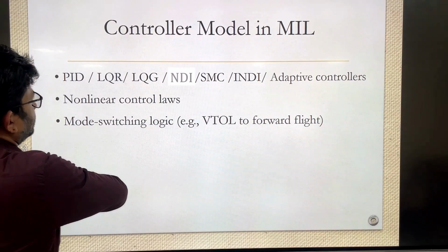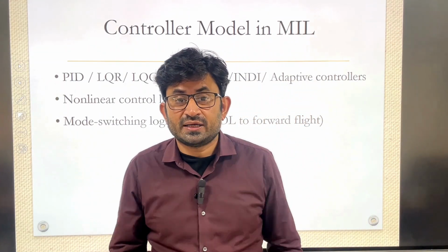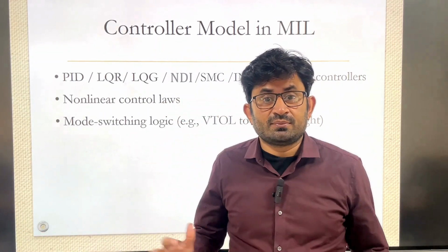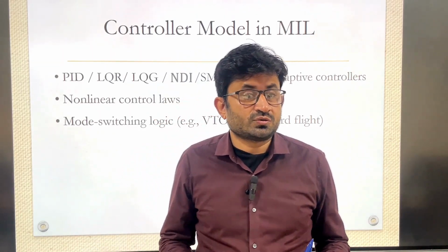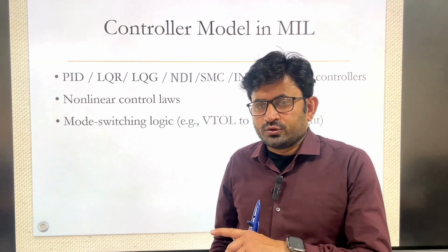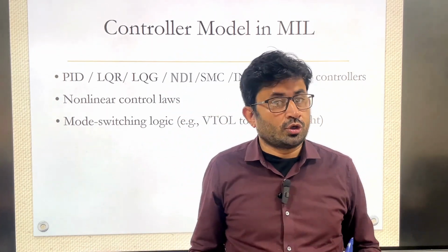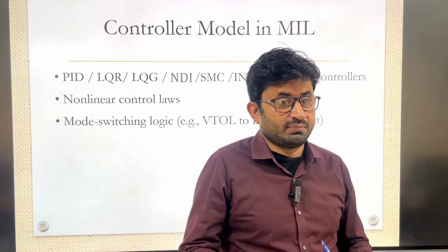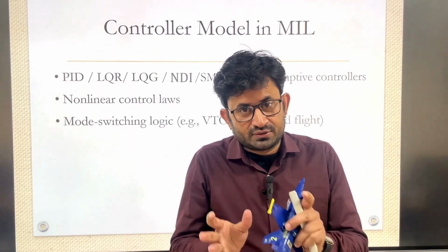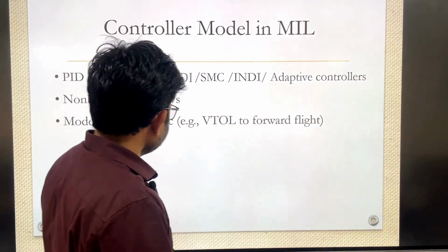At this stage you can do the Monte Carlo simulation also, where you can put in all the aerodynamic models and geometrical models simultaneously, and you can check the robustness of the controller. Because whatever aerodynamic model you have found out so far, using CFD or an analytical approach or both, is not 100% accurate. So you can do the Monte Carlo simulation and see how much perturbation the controller can handle, CG variation, etc.